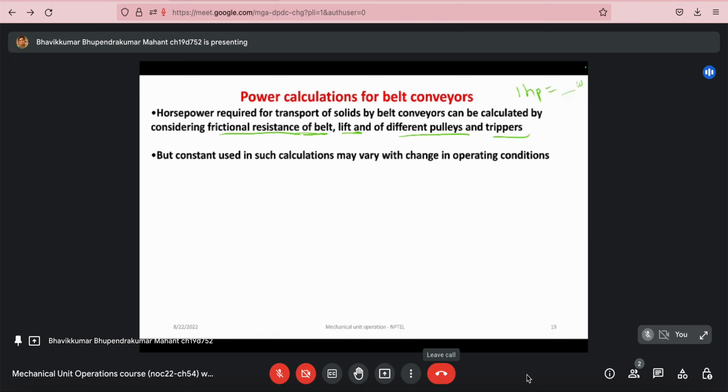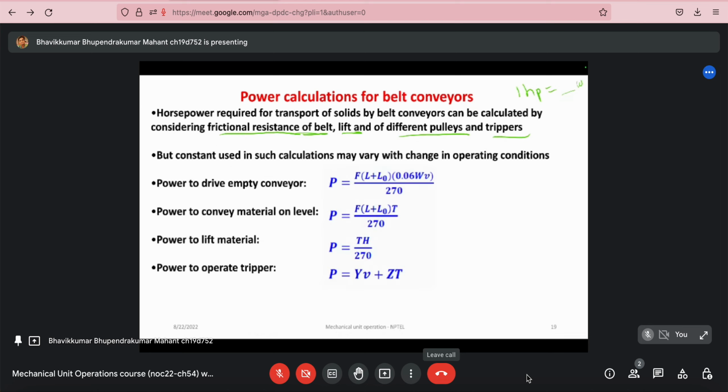We have pulleys and trippers, all of them. But constants used in such calculations may vary with changes in operating conditions. Now these are some formulas which we need to consider for calculation. Power to drive an empty conveyor: this is the equation we need to use. P = F(L + L0) ...